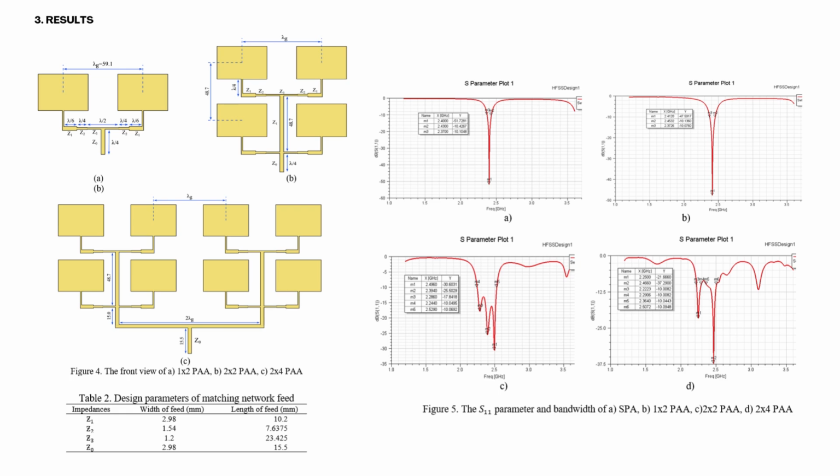for SPA and PAA was carried out by a software product for electrodynamic 3D modeling, Ansys HFSS. The operating frequency of the antenna is chosen to be 2.4 GHz. The substrate is FR4 epoxy with dielectric permittivity equal to 4.4. Following that, we compare the simulation results of all patch antenna arrays, namely parameters such as return loss, bandwidth, gain, VSWR, voltage standing wave ratio, directivity, and radiation patterns.